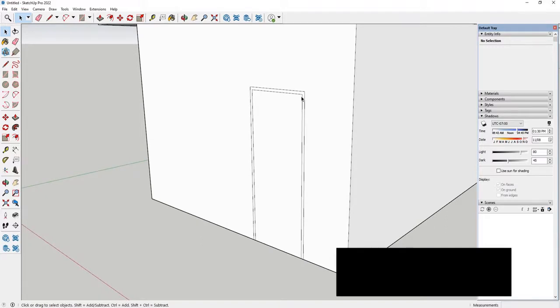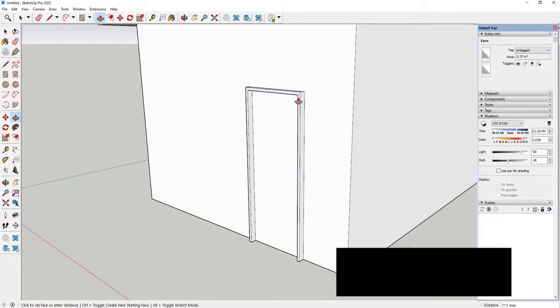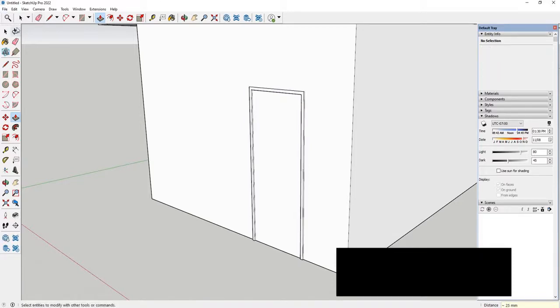It needs a little bit of volume, as it would be framed and it would protrude a little bit from the wall face. So once again, let's grab our push-pull, tap P, select the face of the frame, left click, and we'll say that this door frame is going to protrude an inch or 25.4 millimeters away from the wall face. So let's type 25.4 and hit enter. Now just like that, we've already used a couple simple tools to create a door frame.